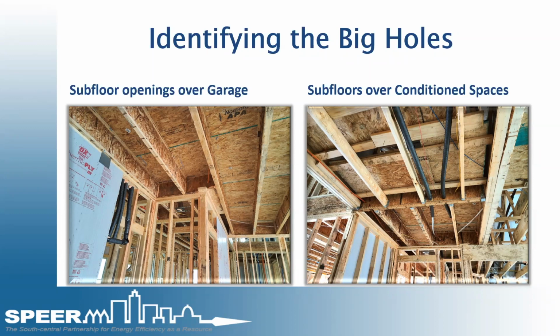They're not looked at as important enough to seal. But if the floor over the garage isn't going to be insulated, then that's an unconditioned space that needs to be blocked off from anything that is a conditioned subfloor, because floors between conditioned spaces are unintentionally conditioned. They are part of that envelope. They do need to be blocked over the garage wall.